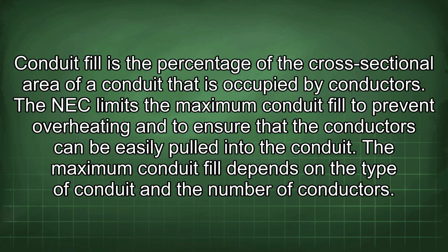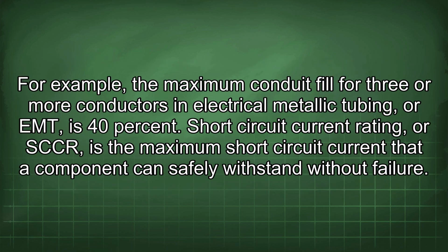Conduit fill is the percentage of the cross-sectional area of a conduit that is occupied by conductors. The NEC limits the maximum conduit fill to prevent overheating and to ensure that the conductors can be easily pulled into the conduit. The maximum conduit fill depends on the type of conduit and the number of conductors. For example, the maximum conduit fill for 3 or more conductors in electrical metallic tubing, or EMT, is 40%.